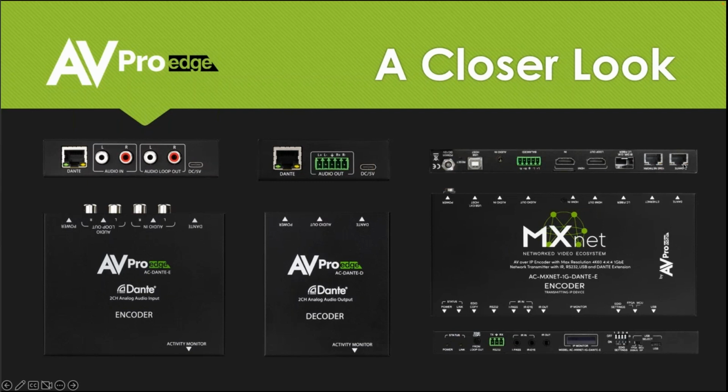This Dante is going to remove or take the two channels that come in through your audio, your HDMI input. Now, if you do come in with more than two-channel audio, it does not downmix. So you do need to set your EDID or your audio source in some other way to send two-channel only, or mono.